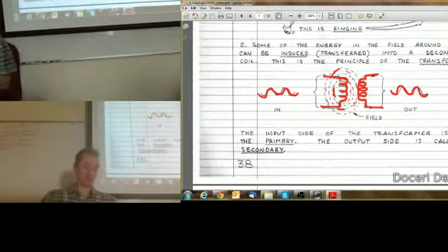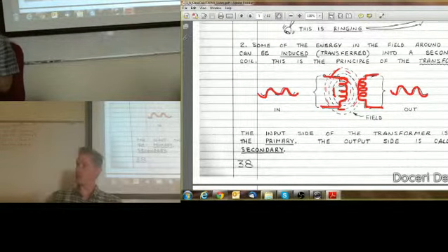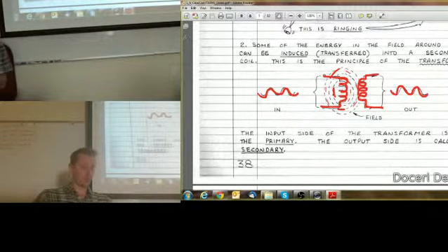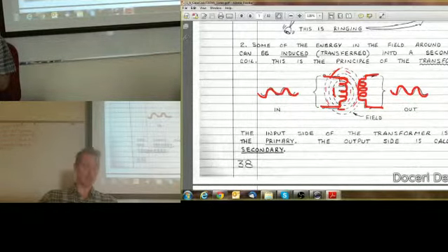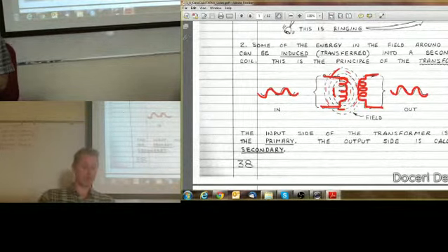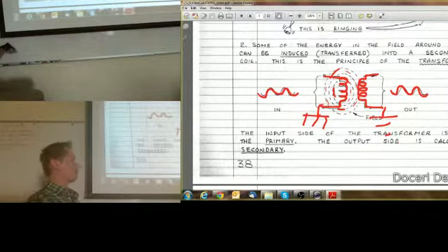And then we say that those two coils are electrically isolated from each other, but magnetically coupled to each other. So we can completely change a ground reference for a system. Some systems need to have different ground references, for example. If you had one ground reference on this side, you could have a completely different ground reference on this side. That's what we call electrical isolation.